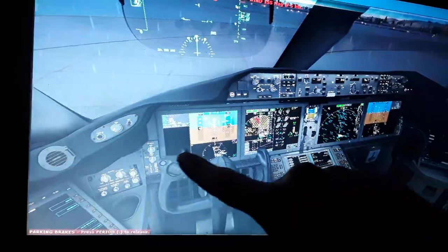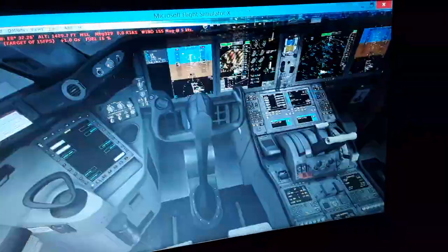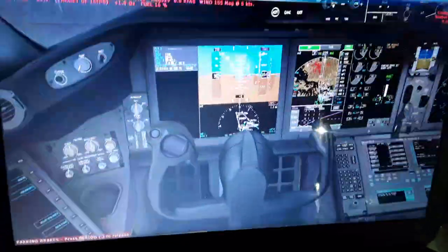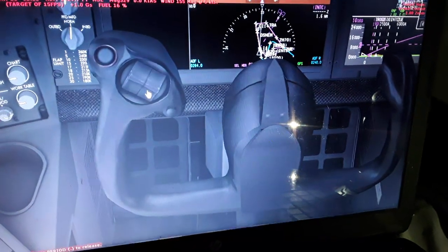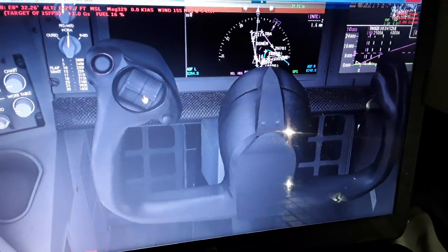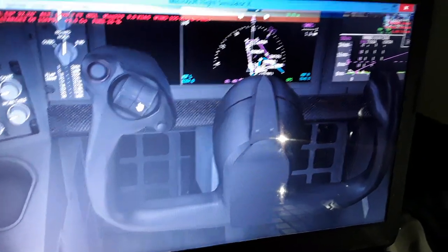We're gonna trim the horizontal tail of the aircraft during the whole time from takeoff, climb, cruise, and approach and landing. You're gonna see that either automatically using the auto trim function from the autopilot flight director system panel and the auto throttle, or we can use the manual trim switch on the control wheel of the yoke of the Boeing 787. You can see here we can trim the horizontal tail of the aircraft like this, trim up and trim down, having this switch here. So this trims the horizontal tail of the aircraft, trim up to pitch up and trim down to pitch down the other way.